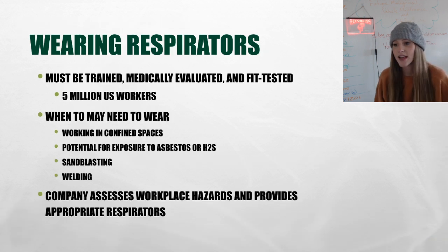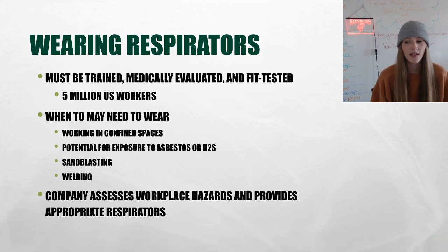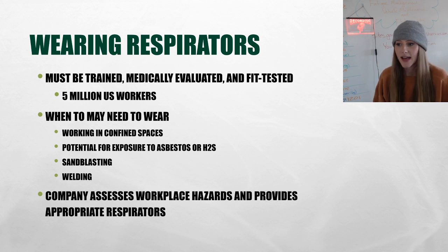Wearing respirators: in order to wear one, you must be trained, medically evaluated, and fit tested for those respirators. If you get fit tested in a certain make, model, and size, that has to be the same make, model, and size you wear out in the field. You can't be fit tested in a certain one and then take a different one out in the field.